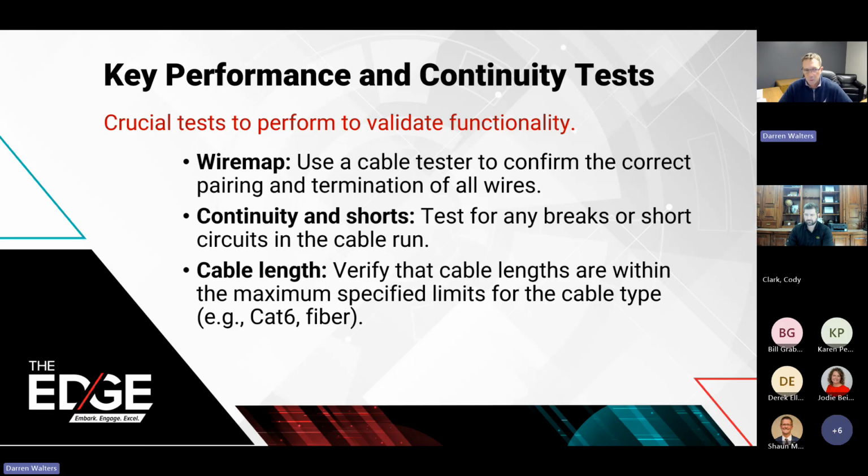The final thing that's pretty important is we can test cable length. So if we put the test equipment in one end and the other end at the rack, when we run that test, we can say, okay, this is 250 feet. So it falls within the threshold of what we want, or for some reason, this one's like 400 and some. And in some installations, you'll have some that are a little bit longer. Then you can make a decision, okay, do I need to do something different, or do I just document that this run exceeds the limit, and it probably won't certify.